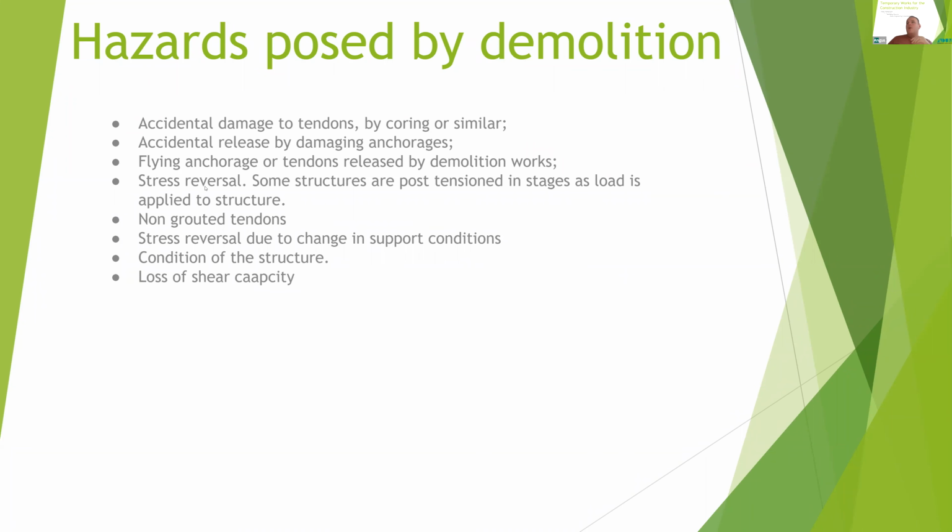Stress reversal. Some structures, the post-tensioning effects are added in tandem with dead load being added to the structure. So for instance, if you had a big transfer deck above a railway line or above some other item, and you're building a 30-story building, as another story is added, it's not uncommon for another tendon to be tensioned up.